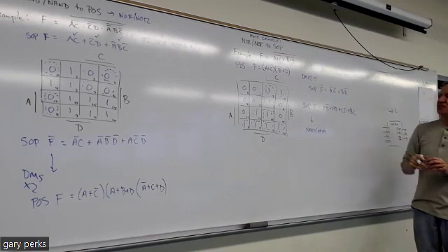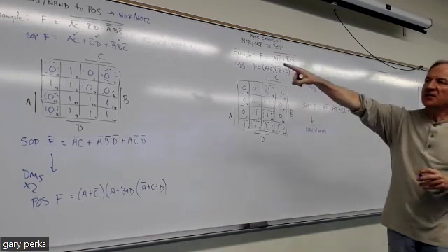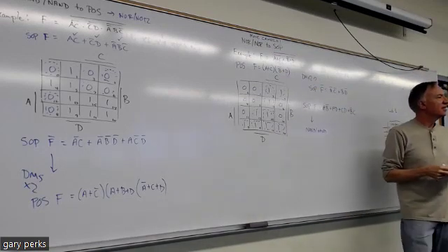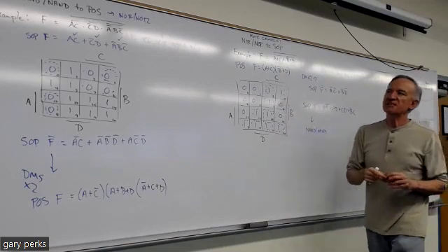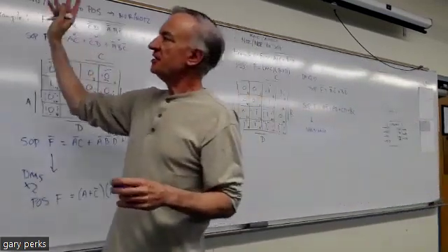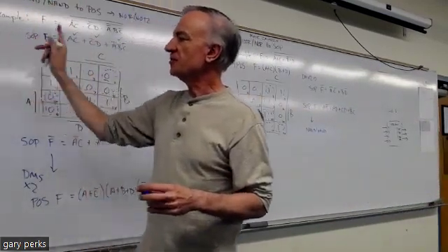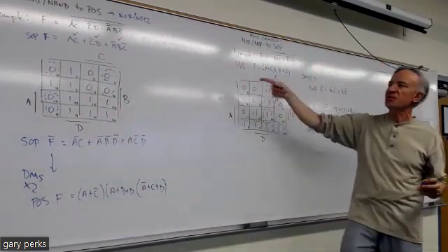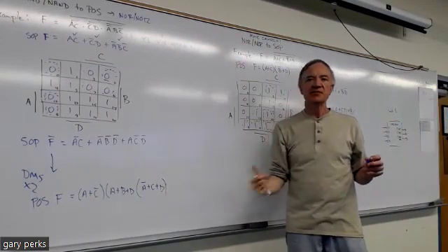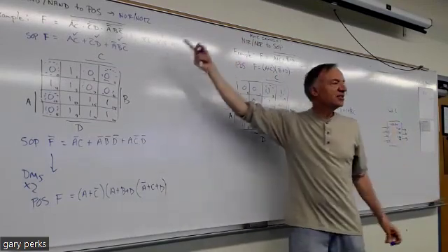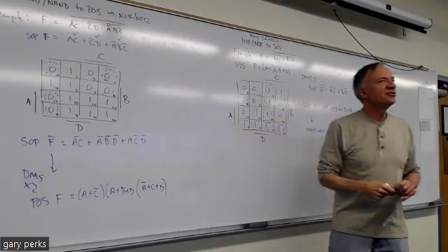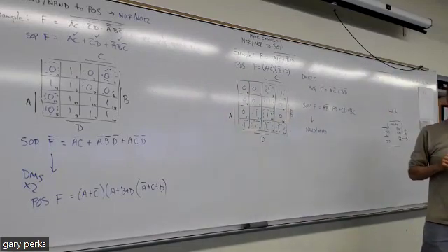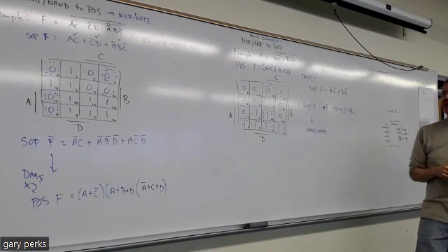Okay, so you see that's our reduced SOP graph, and like I said, you could then do what we did over there to get NAND if you wanted to. But the thing to take from this again, NAND, SOP, not so hard, NOR, POS, not so hard, but when you gotta go NAND to POS, or you gotta go NOR to SOP, you have to go through a truth table. Right, and that's when you're using things you learned earlier last week. Okay, so this is a good type of review problem.